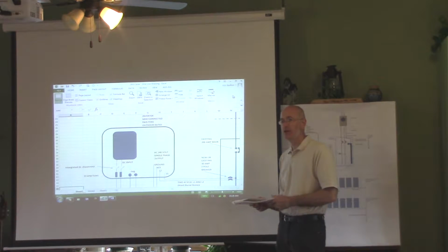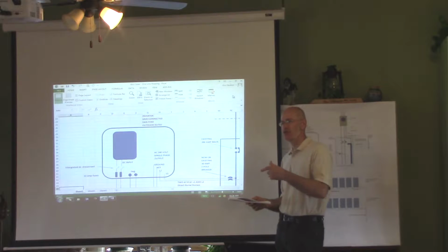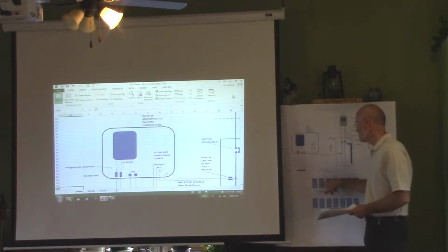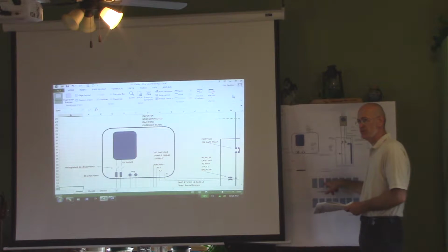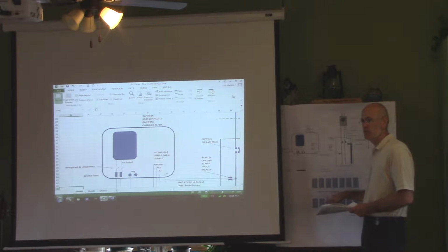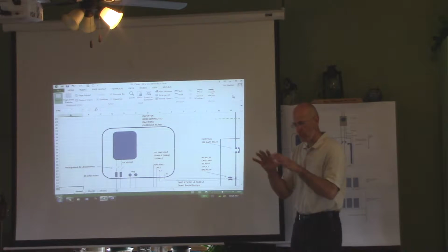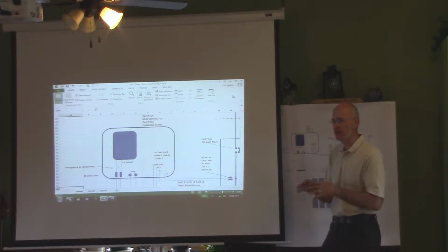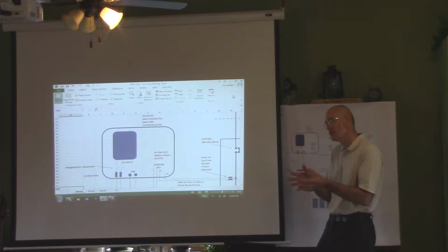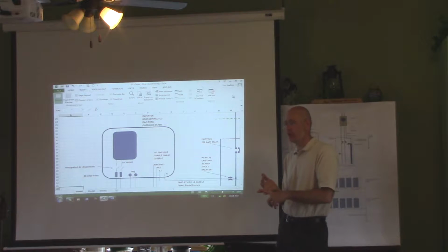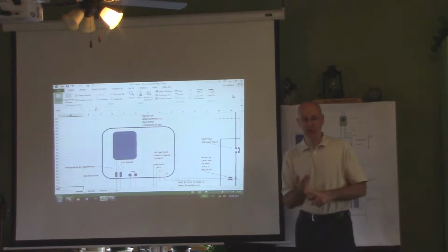There you go. A lot of engineers make that mistake, and you just size it for what the nameplate is. Well, the nameplate on solar panels is sized at full sun, 70 degrees. So when you buy something electrical, what is the parameters its intention is for? We have to stay within those boundaries. If we go outside of those boundaries, then we're setting up a dangerous situation that can cause a fire and burn your house down. That would not be being a good steward.